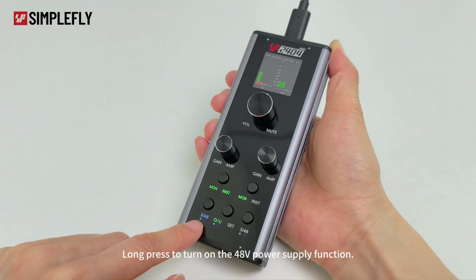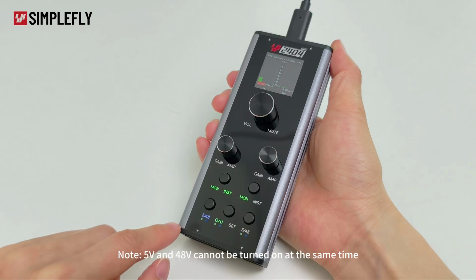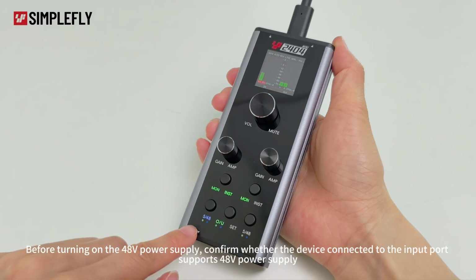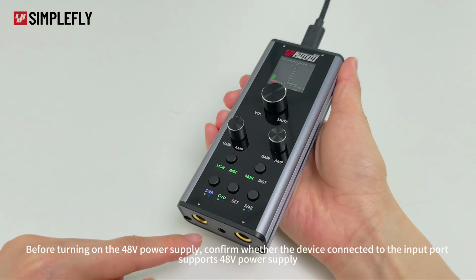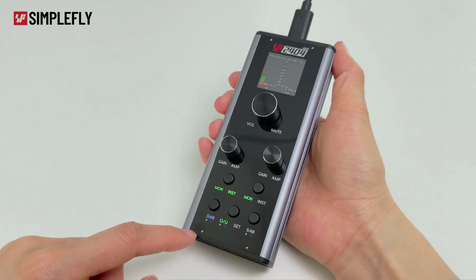Long press to turn on the 48 volt power supply function. Note: 5 volts and 48 volts cannot be turned on at the same time. Before turning on the 48 volt power supply, confirm whether the device connected to the input port supports 48 volt power supply. Otherwise, it may cause damage to the equipment.